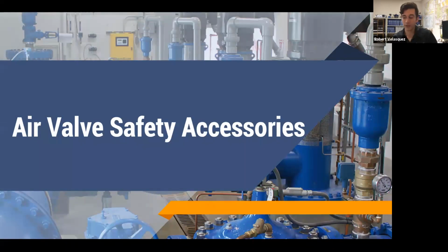These air valves are put throughout water distribution systems. When they're put in a pump house, like in this picture in the background, you can see on the right side that is an air vac valve, because these are pumps pushing out on these pump control valves. This air vac valve is letting air out when the pumps start up and letting air in when the pumps turn off or if they were to lose power. Right here in this vault, they're just being piped around and releasing into this pump house because it's just in the house.